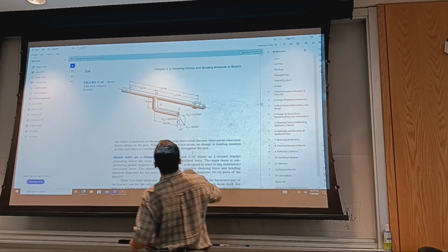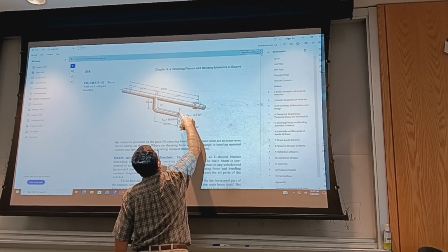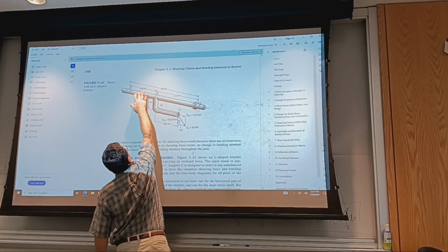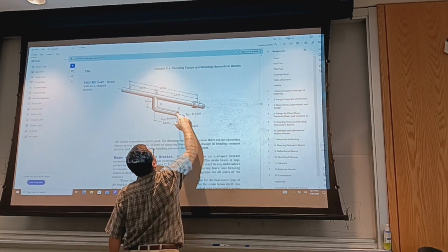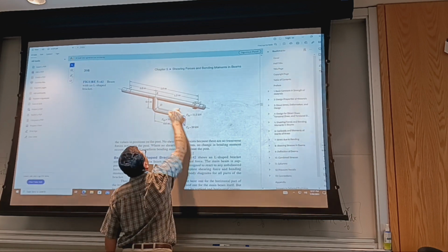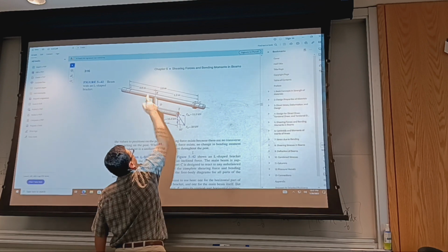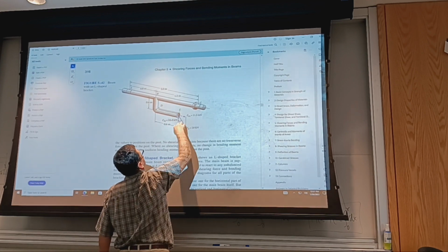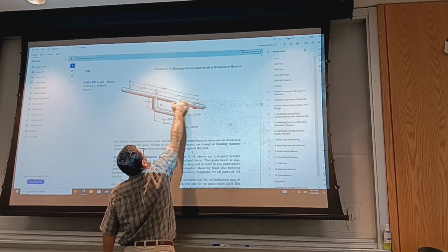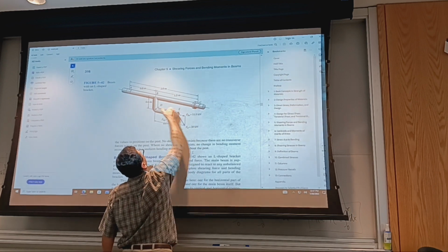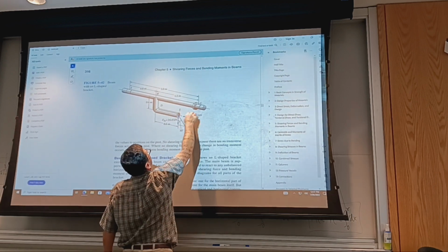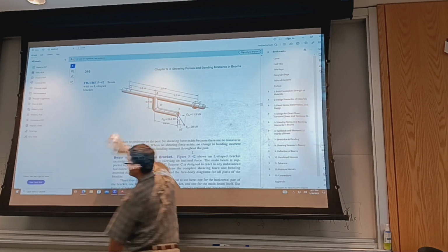I did some horizontal and vertical movement. Well, you can work with components. So I take this component, place it here. Again, we're talking about the long horizontal ABC piece. Take this, move it here. Take this, move it here. But because I shifted, I need to introduce a moment that is 0.6 times the vertical component. And because I shifted in line, I need to add a moment the other way, which is the horizontal component times this distance. Does it make sense?